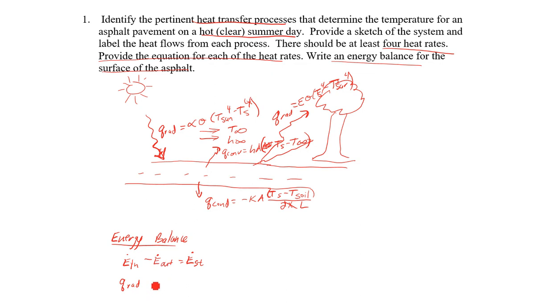So one thing flowing in, what's going out? Minus Q convection, minus Q rad, let me call it 2 maybe, minus Q conduction. And what does that equal? It's going to get us our rho Cp dT/dt, or our storage term here, that is how our temperature changes with time.